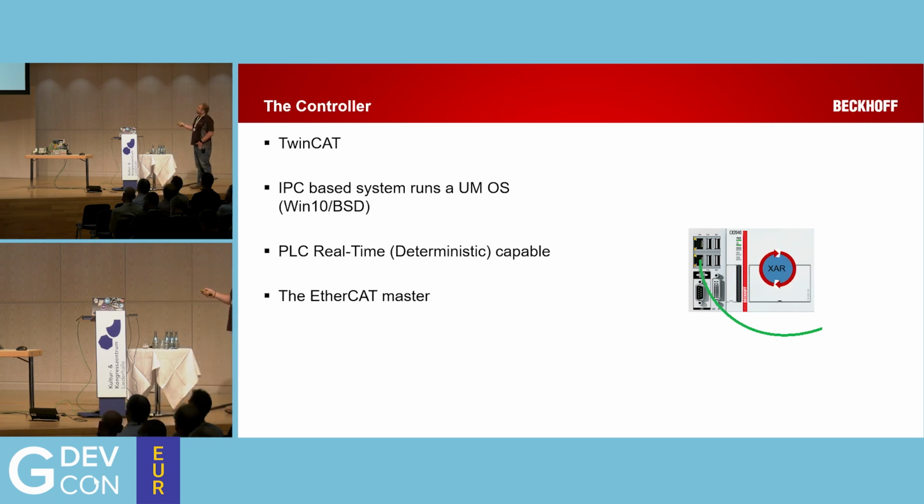There are devices in the world that aren't all Beckhoff, from third-party companies as well, that have EtherCAT slave interfaces on their controllers. What that means is you can have a high-level PC and then divide it up into a load of PLC units that are then EtherCAT slaves to that high-level PC. So your high-level PC gives you that grand reference clock, and then it filters down through all the other PCs, and they then take their time reference from that one.